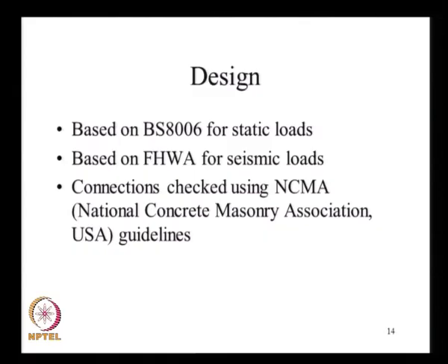And as we already know, the BS code does not talk about the seismic loads, and so the seismic load factors were taken from the Federal Highway Administration design guidelines only for the purpose of estimating the seismic loads.